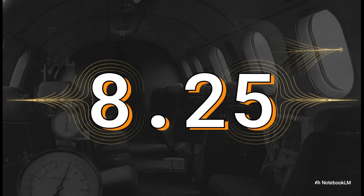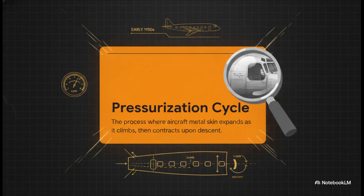This internal pressure effectively turned the thin metal fuselage of the aircraft into a giant pressure vessel. Now, this brings us to what's known as a pressurization cycle. Every single time an aircraft climbs and descends, it completes this living, breathing mechanical process. The metal skin of the fuselage physically expands just a little bit as the plane climbs, and the internal pressure pushes outward, and then it contracts again after landing. This repeated expansion and contraction is a totally normal part of flight.